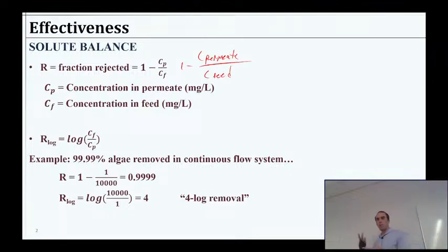So again, we're just using the permeate, the feed, and the retentate as our catch terms for where the water is going in our membrane. And if you think back on our last problem, we didn't have a flow rate for the retentate. We just stopped at some point. But this equation can still apply, right? We could go back a step and say, okay, well, what was the concentration in the permeating fluid? And that'll tell us something about the comparison to the feed.